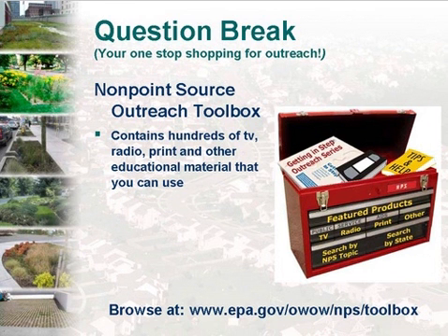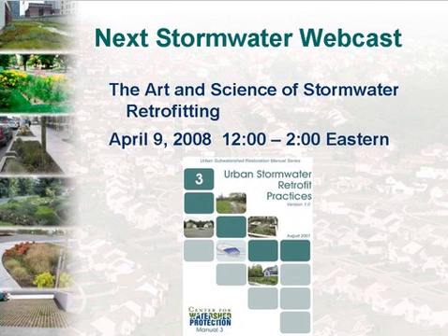So stay with it. Get whatever storms you can. Keep the relevant regulators very well informed of your effort. And perhaps when you do collect a storm that may not comply strictly with all EPA's recommendations and other recommendations for design storm metrics, run by the relevant regulators what kind of data you do have and see if that would be acceptable as a substitute. Those would be my thoughts.